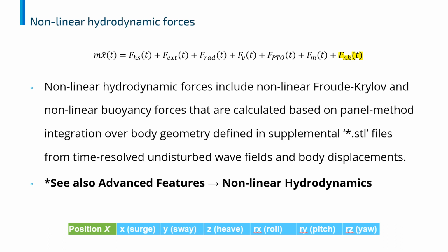Another force that can be activated within WEC-Sim are the nonlinear hydrodynamic forces. These include the nonlinear Froude-Krylov and nonlinear buoyancy forces that are calculated based on integrating the instantaneous pressure over the body geometry. The body geometry is defined by a supplemental .stl file, and the pressures are calculated from the time-resolved undisturbed wave fields and instantaneous body displacement. For more information, please visit our Advanced Features Nonlinear Hydrodynamics description on our documentation webpage.